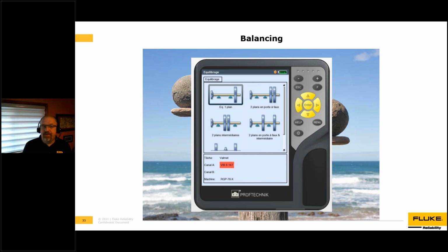One of the tricks to successfully achieving a balance on rotating equipment is to remember that it is vital to rule out every other source of fault energy. Looseness, coupling issues, bearing issues, alignment, all of it, before you attempt your balance.